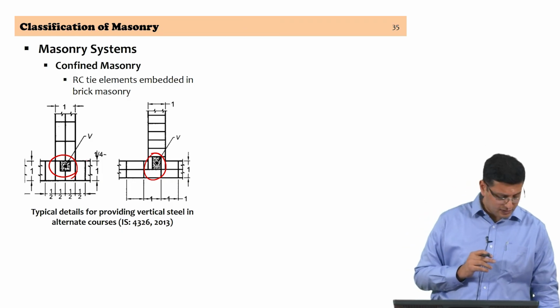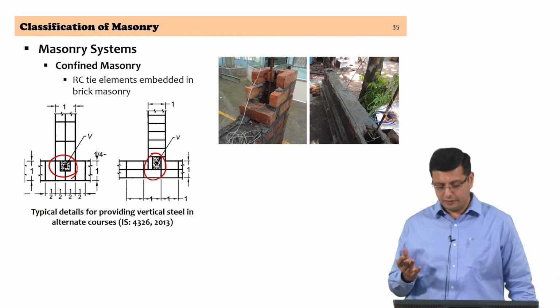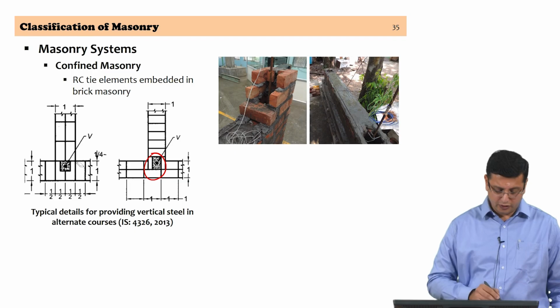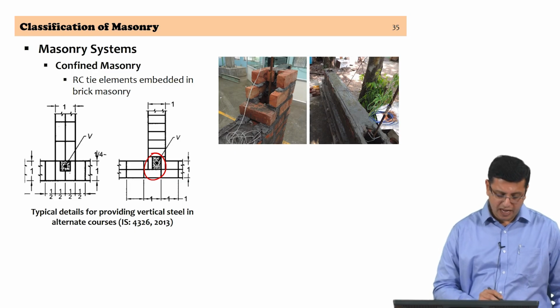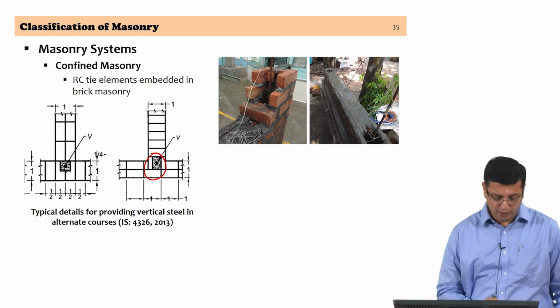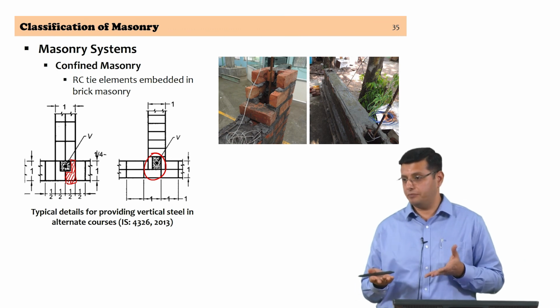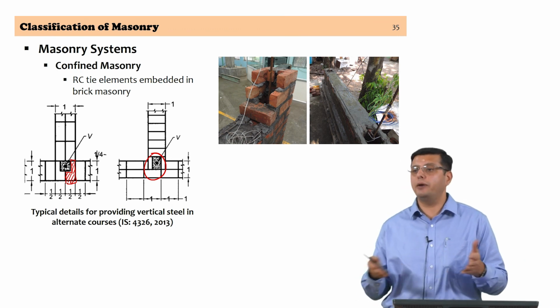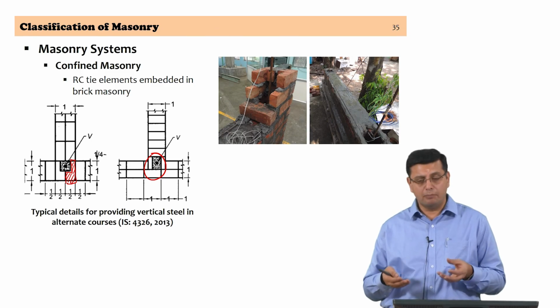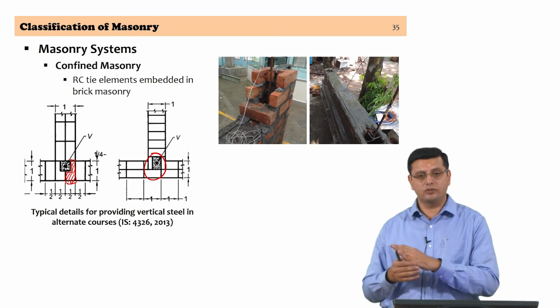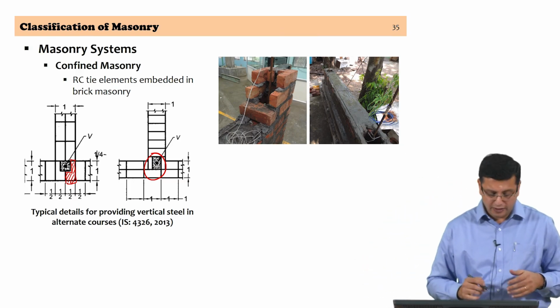However, this construction is quite challenging because if you look at the drawing, the shape of the brick that you require is rather difficult to achieve unless you are going to be manufacturing the brick in that shape, but it is actually uneconomical to manufacture brick in that shape. Numbers will be low, and the time taken and the cost for some bricks will be more than the rest of the bricks. So, it does not make sense to create bricks like that.